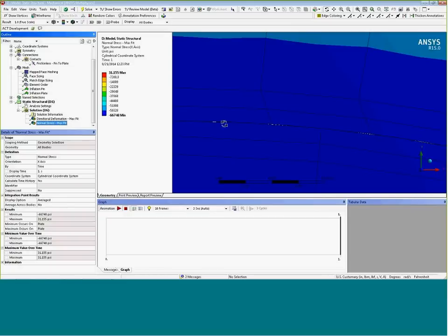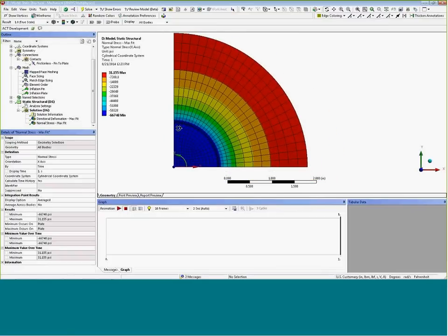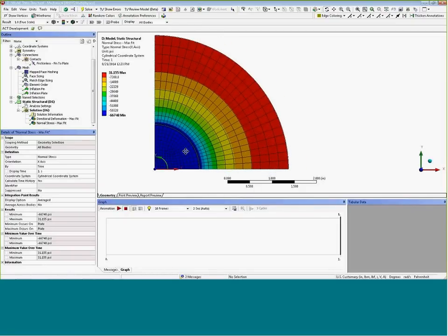So it's really segment-to-segment based contact. And if we use this contact, now you can see this result is 66.7. I think that's the best stress we've got so far in terms of accuracy. And it's also very smooth around the circumference, and this is a dissimilar mesh as well. So just showing that the difference in that contact detection makes a big difference in the results here.